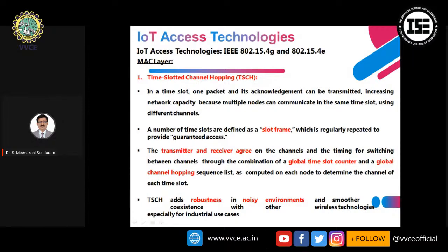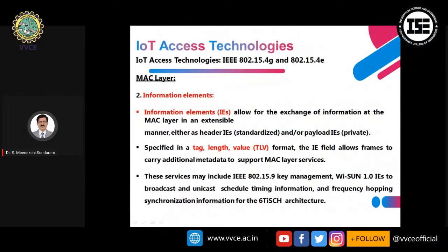and a combination of the global time slot counter and global channel hopping sequence list is computed in each node to determine the channel of each time slot. So TSCH is robust and suitable for noisy environments and smoother coexistence with other wireless technology, especially for industrial use cases. Similarly, the MAC layer information elements include the information IEs. We have a specified type-length-value TLV format, which allows frames to carry additional metadata and support MAC layer services. And these services may include key management.